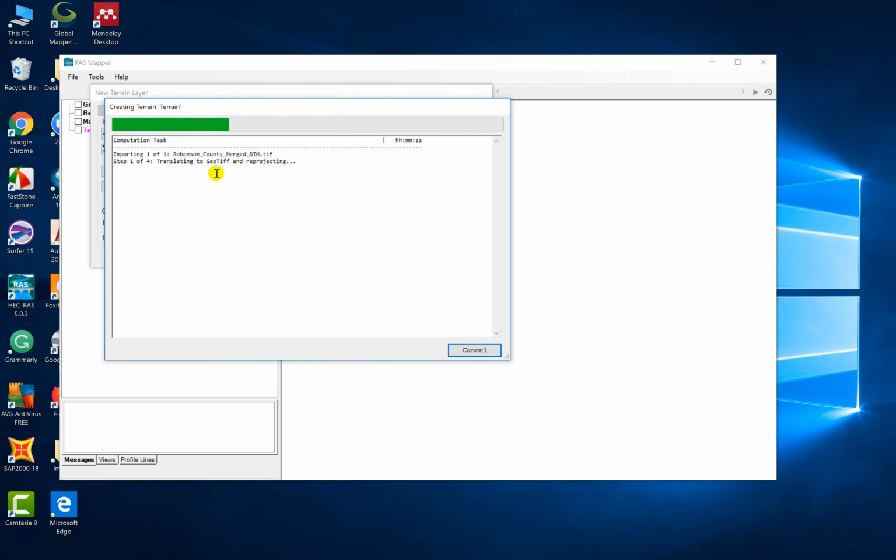And after defining the 2D flood area, we have to define boundary conditions. For the 2D flood area, you don't define boundary conditions inside. All is outside. You may know the discharge at some point inside, but it will not be helpful. You should know the points outside this 2D area. So you mean that for defining the boundary condition, we just need to select the outside part? Yeah, I'm going to show you here.